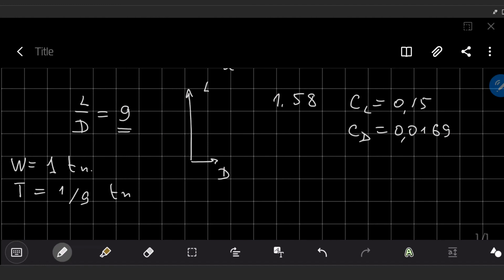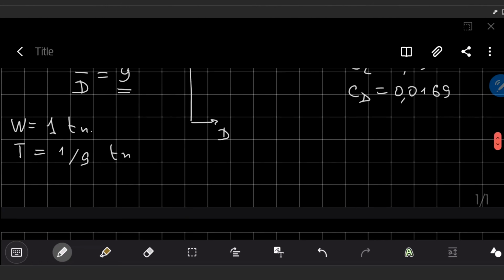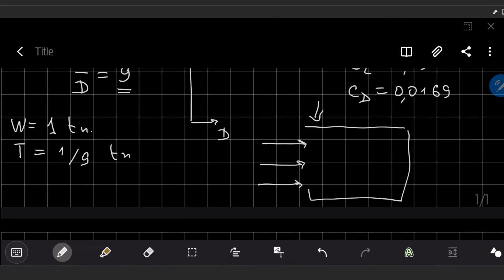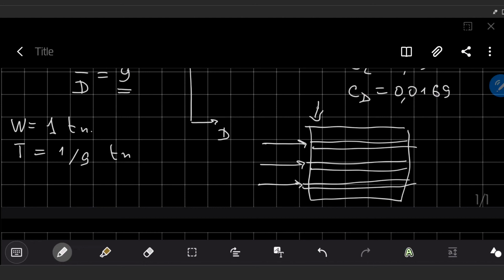But installing every piece of equipment, we are always increasing the drag of the airplane. For example, the intercooler is a heat exchanger, where you inject the air from one side and it exits from another side inside the box. There are channels here, air passes through the channels, and it cools down. Hot air from one side becomes colder on the other side.